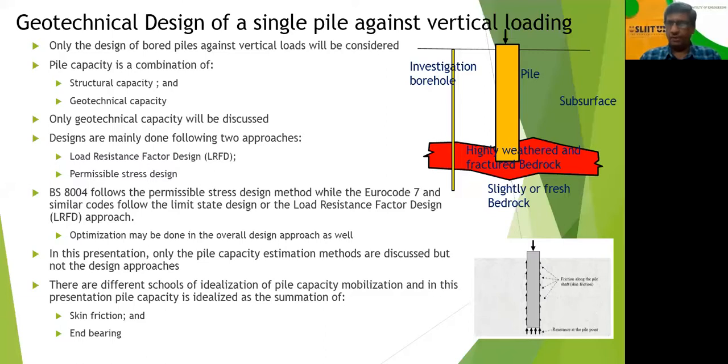So in my opinion, we can optimize the design of the piles using the design approaches as well. Right now we are using the permissible stress design approach. If you move on to the limit state approach, then we may be able to optimize that. But that is for a different discussion.